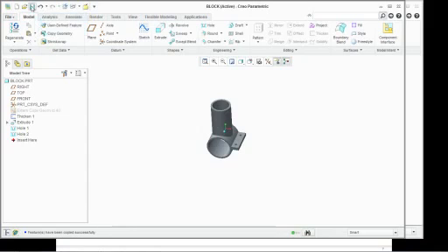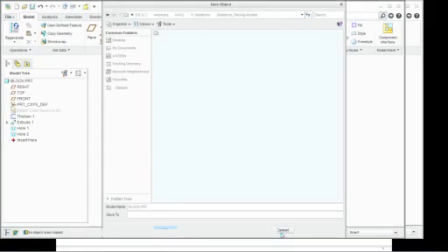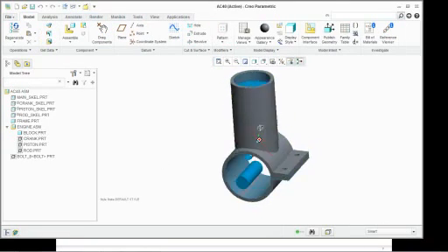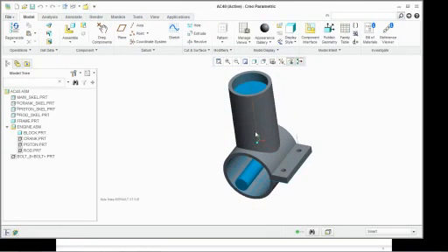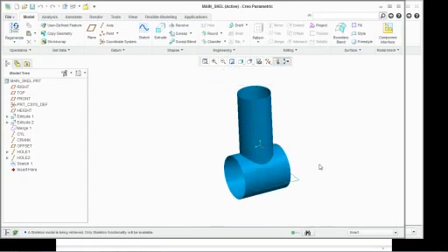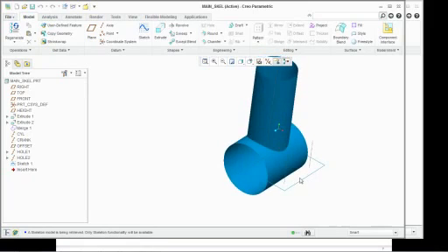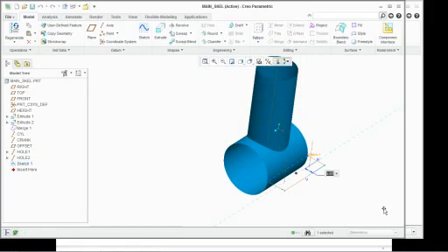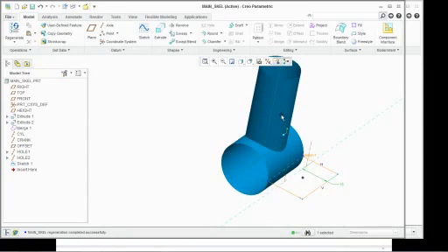Well, the really cool thing about this is I'm going to go in and let's flip back over to the assembly. Notice now I could go in and do that for all of these components, which you guys would probably get bored if I did that, and we don't have enough time to do that anyway. But if I go into my main skeleton, which everything's based off of, we created an almost identical skeleton to this earlier. Let's say, for example, I want to edit this. So instead of 5, let's change this to 15.